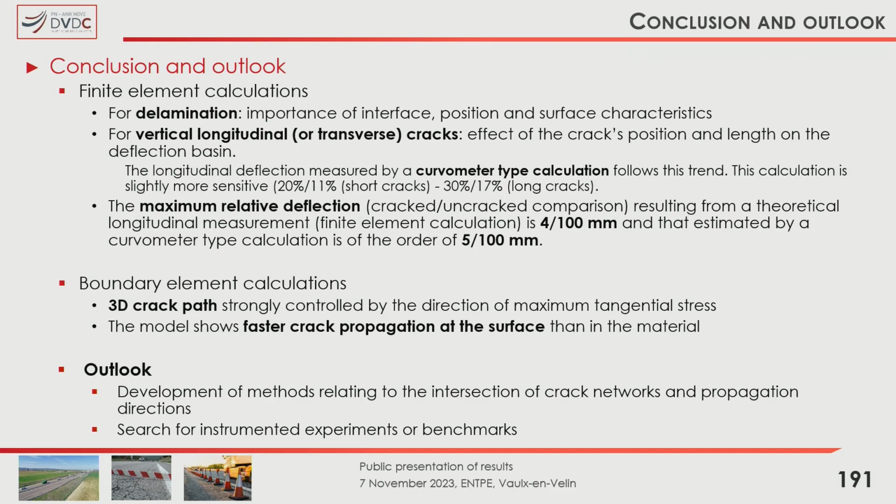For the structures, we get deflections of 10 to 15 hundredths of millimeters. For the boundary elements, we did a 3D crack path, which was controlled by the maximum tangential stress, and the model shows that there is faster crack propagation at the surface than in the material itself.